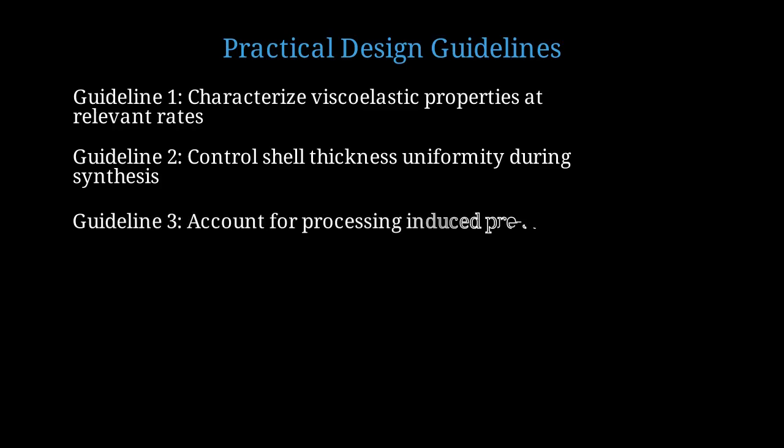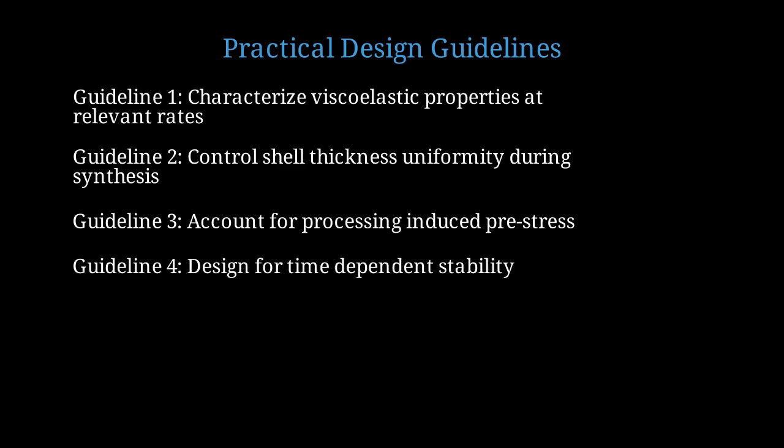Guideline 3. Account for processing-induced pre-stress. Annealing or controlled drying can minimize residual stress. Guideline 4. Design for time-dependent stability, not just instantaneous loading. Your capsule must survive over its entire lifetime. Guideline 5. Test capsules under realistic conditions including temperature, humidity, and chemical environment. Laboratory tests may not reflect real use.